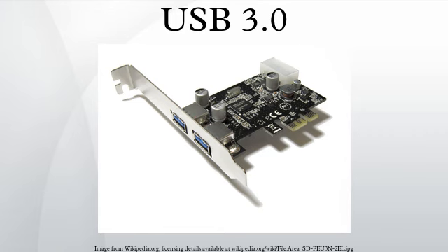Support for rotating media: the bulk protocol is updated with a new feature called Stream Protocol that allows a large number of logical streams within an endpoint. USB 3.0 has transmission speeds of up to 5 Gbps, which is 10 times as fast as USB 2.0, before taking into account that USB 3.0 is full duplex whereas USB 2.0 is half duplex, giving USB 3.0 the potential total bandwidth, if utilized both ways, of 20 times that of USB 2.0.